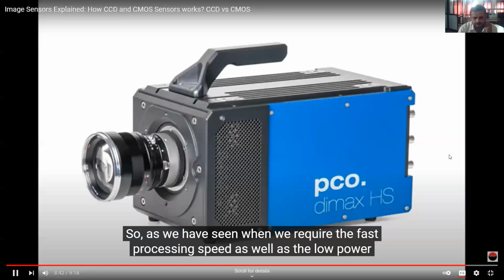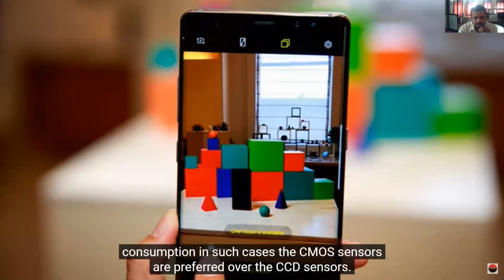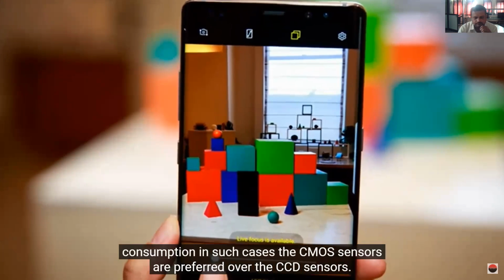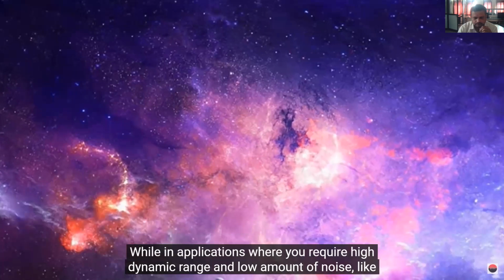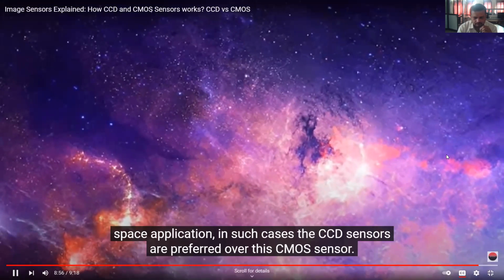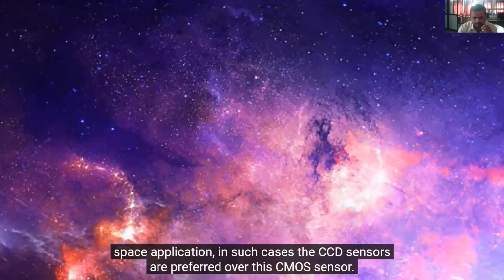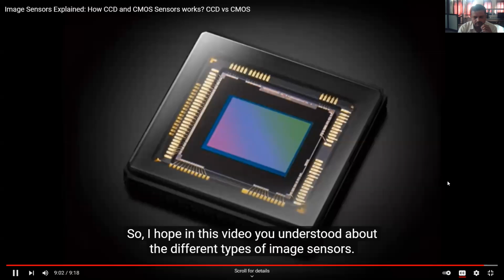As we have seen, when we require fast processing speed as well as low power consumption, in such cases the CMOS sensors are preferred over the CCD sensors. While in applications where you require a high dynamic range and a low amount of noise, like a space application, in such cases the CCD sensors are preferred over the CMOS sensors. I hope in this video you understood about the different types of image sensors.